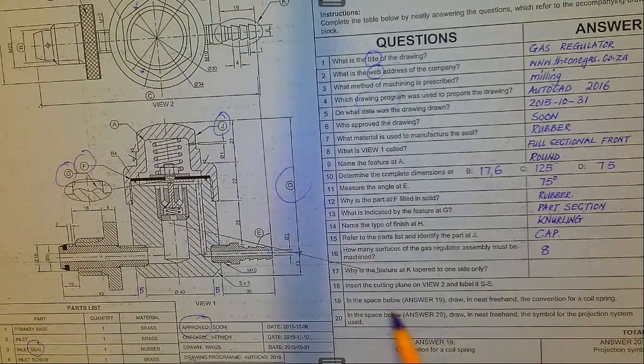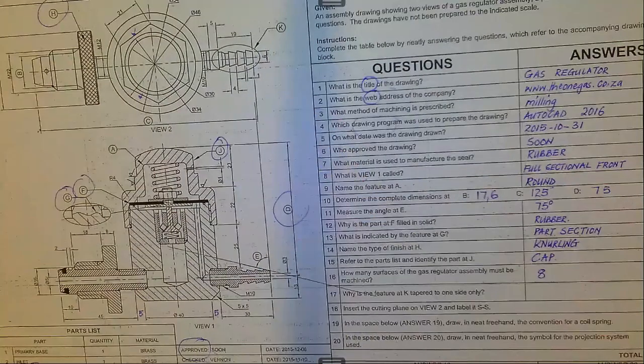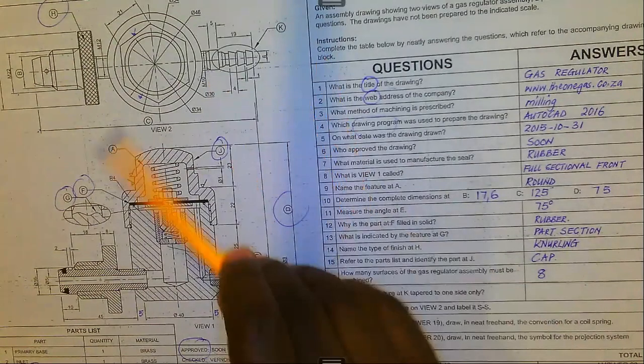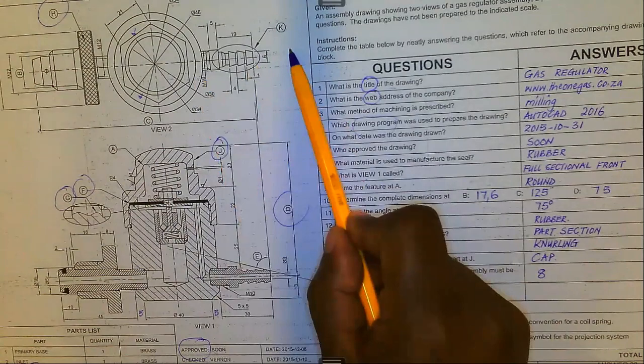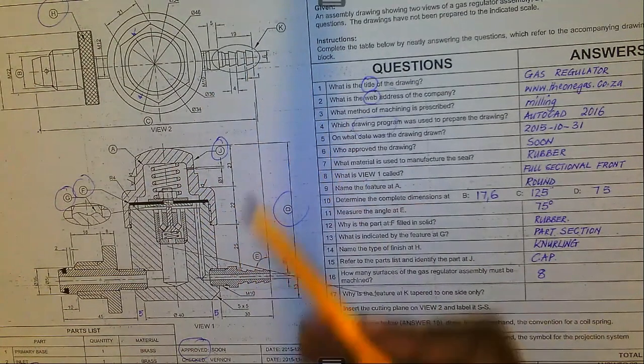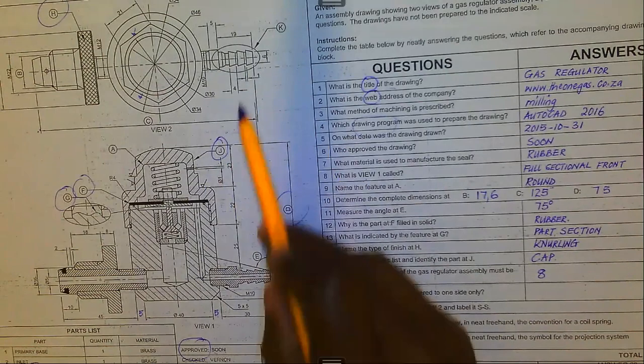Why is the feature at K tapered to one side like that? It's here. It's tapered on one side. In most cases, when you have an application like this in an engineering component or part, you want to make sure that the movement is basically one way, and when it tries to come back, it is held by that. You can force it in, and in most cases it will be forced into rubber or something like that. To pull it back, you need extra effort. So the reason could be that you want to keep that item in position, to avoid slipping out, which is now stopped by that.